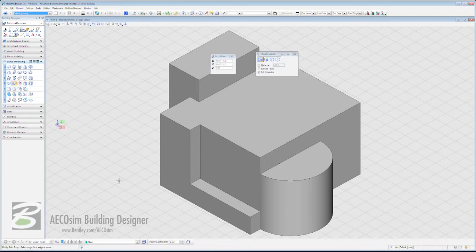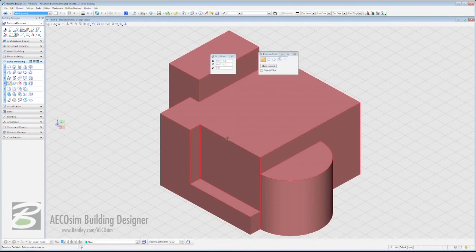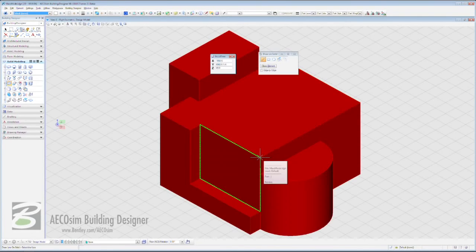That's it. You can also use Draw on Solid to very quickly come in here, and if you want to line it up with a particular face, all you need to do is on the way that you're describing, hit your Enter key, and then come across here, and you can see that construction line being thrown out. You're going to click there and click once more.